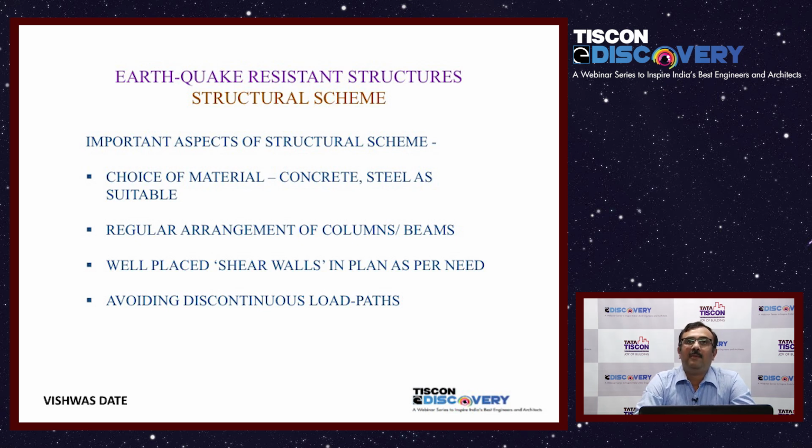Shear walls are key elements of earthquake resistance, and they need to be planned carefully. It is not necessary to have shear walls everywhere possible. It is important to place them well and make the best use of them so that we maintain the best symmetry in the structural system, even if it is not in the architectural system.